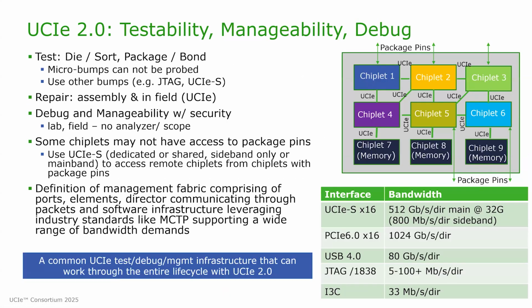Now with UCIe 2.0, we addressed the many challenges to realize the vision of an open plug-and-play chiplet-based ecosystem. There are a few aspects: testability, manageability, debug. These need to be addressed at the SIP level and even at the platform level.